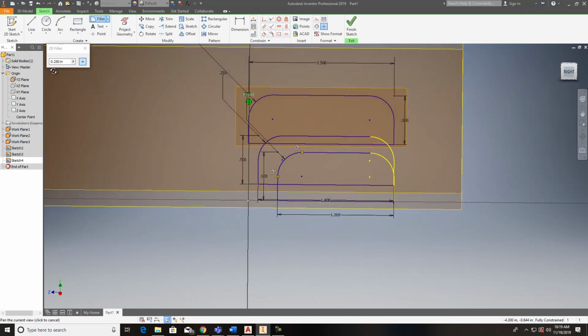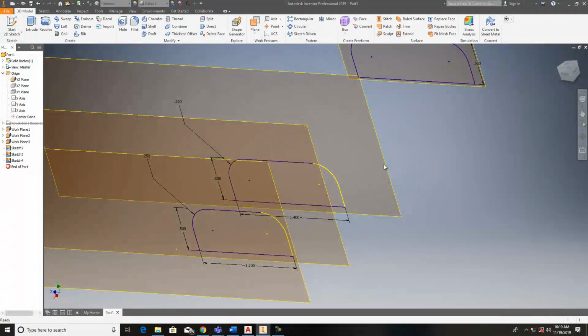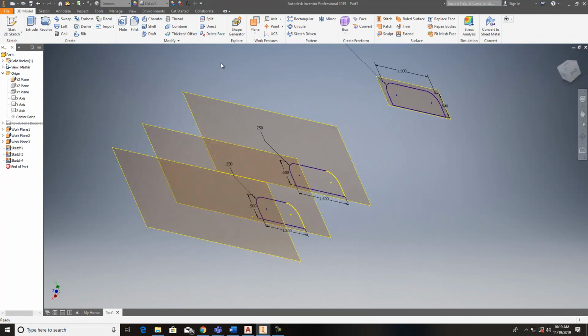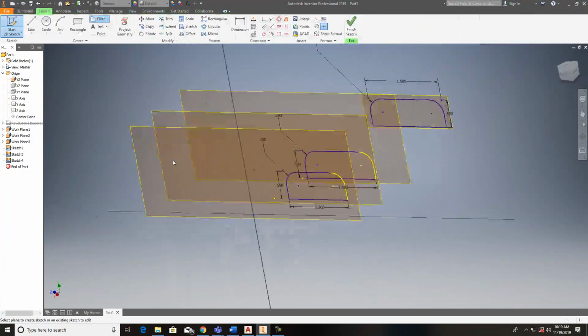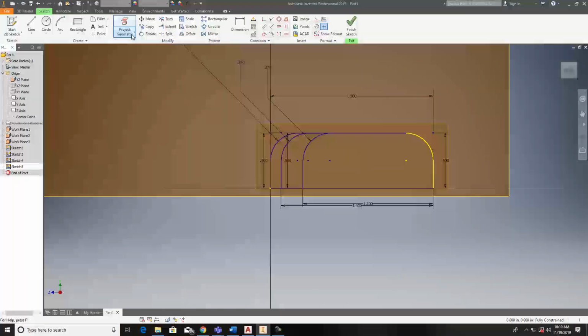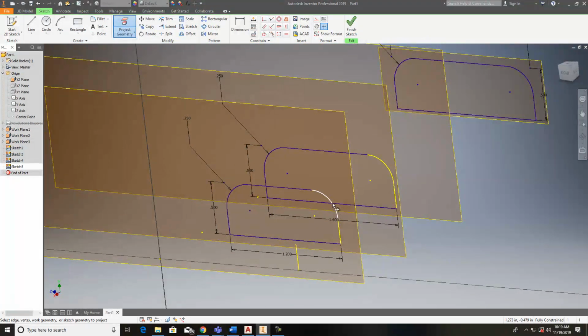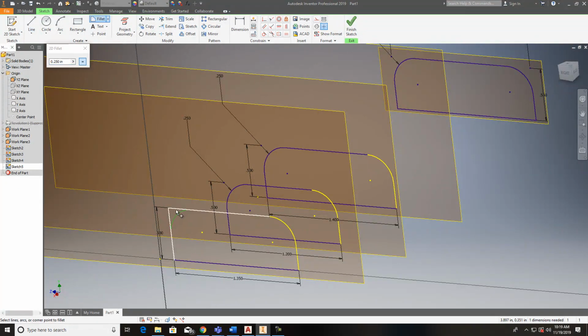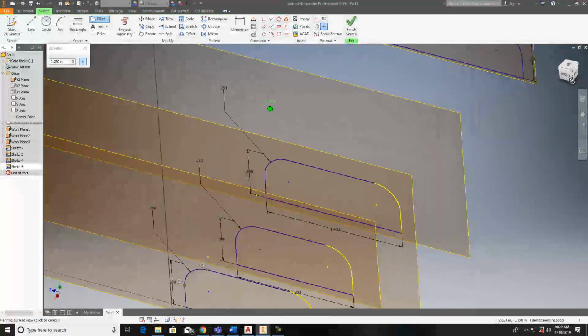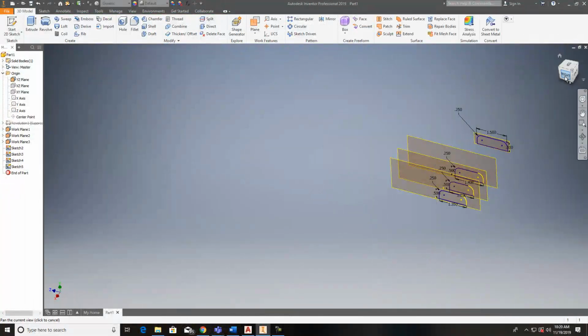Alright, we're getting closer, guys. Finish the sketch. It brings up where I can see my next sketch, and I'll go ahead and make it, and boom. And now I can project my geometry, and I turn so I can see what I'm doing. I want to project this and this, and that's all I need, because I can come down here and hit line, get that lined up, 1.35 up vertically, 0.5 back over and touch that point, fillet it.